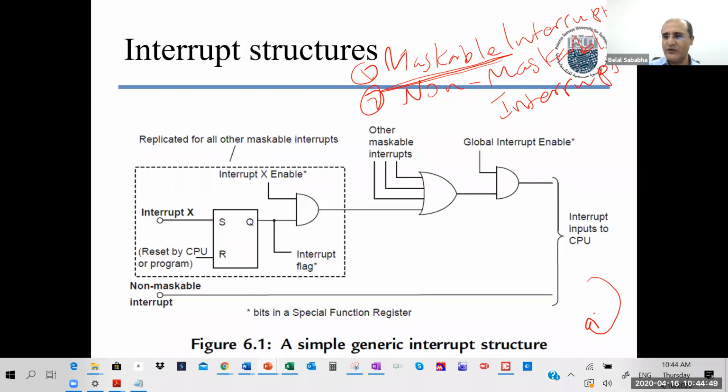When you're in the middle of something important, you don't want the external interrupt on port B0, tied to somebody ringing a doorbell or opening a door or whatever, to interrupt you, because what you're doing is more important than the interrupt cause. So you can disable an interrupt at some pieces of your code. That's called maskable interrupts.